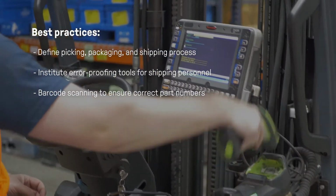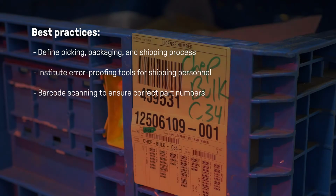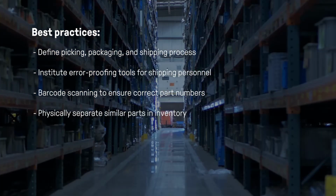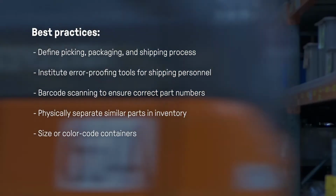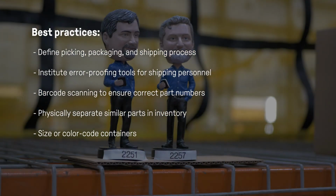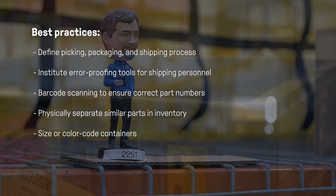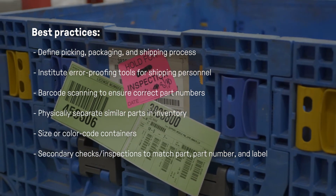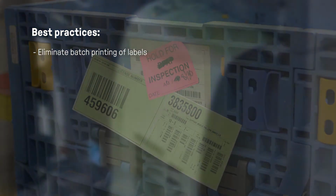Automate the shipping process by implementing a barcode scanning system to ensure correct part numbers. Physically separate similar parts in inventory, or pack in different size colored containers to minimize risk of picking the wrong part. This includes similar geometry, left-right hand parts, and parts with similar part numbers. Add secondary checks and inspections to ensure that part number and the label all match. Eliminate batch printing of labels to minimize the risk for mislabeling of boxes.